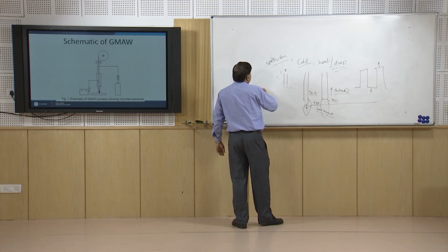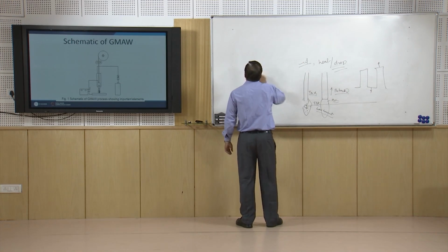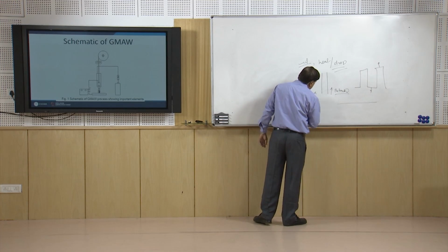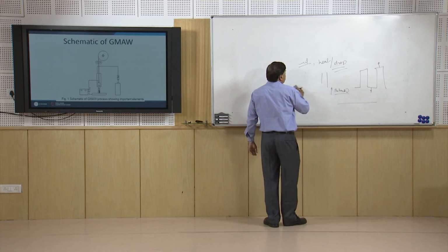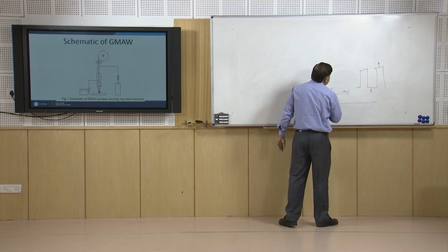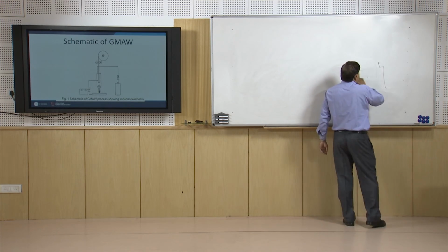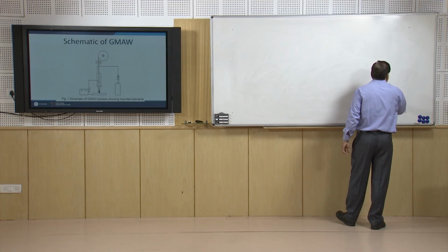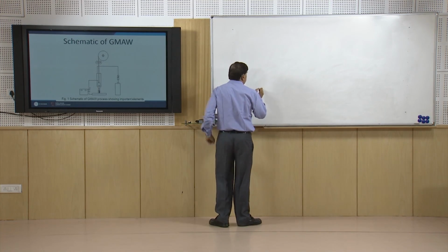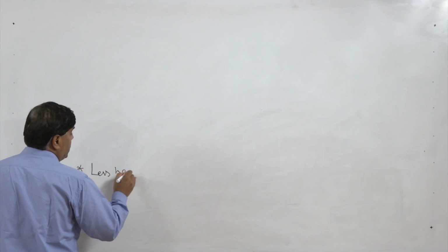The unique feature of this is that the pulsing helps to reduce the heat input, and when we see the transfer in the short circuiting way, when the current value is very low, the transfer is very spatter free, very smooth. So, this feature facilitates two things: very less heat input,